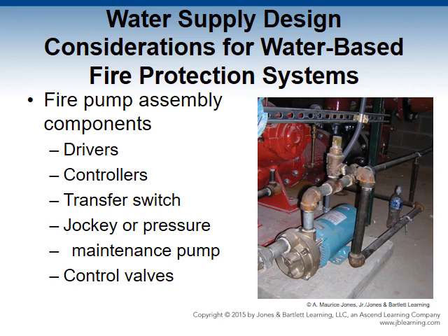Eccentric or concentric reducers and increasers. They are used when the fire pump suction and discharge flanges are a different size than the system piping. They ensure that the water flows in and out of the pump without creating turbulence that would cause cavitation and air pockets, rendering the system inoperable.